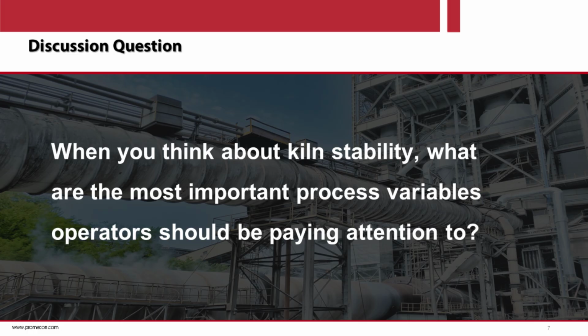So of course you have to follow that, like everybody does. Now it's the oxygen level, the CO, and the nitrogen oxide level that will indicate the combustion efficiency and the air-fuel balance. And the nitrogen oxide will also be a good indicator of the temperature of the core of the flame at the burner. To reduce the NOx emission, you will have to reduce that core temperature of the flame.